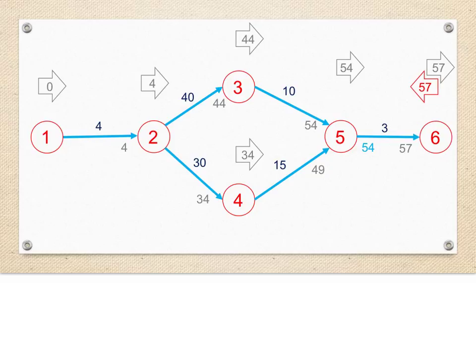We then subtract the 3 days of task 5.6 to get a latest start time of task 5.6 of 54 days, meaning the latest time we can start the geotech report writing is 54 days after the project begins.